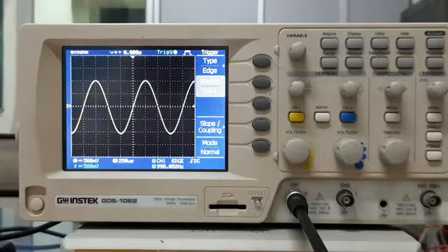So at which, basically, the oscilloscope measures the signal, and then you need to tell it some reference, in terms of measurement and in terms of display, at what amplitude it should treat it as a signal and not noise, because it could happen that you have a signal which also has noise and you only want to see the signal but not the noise, right?